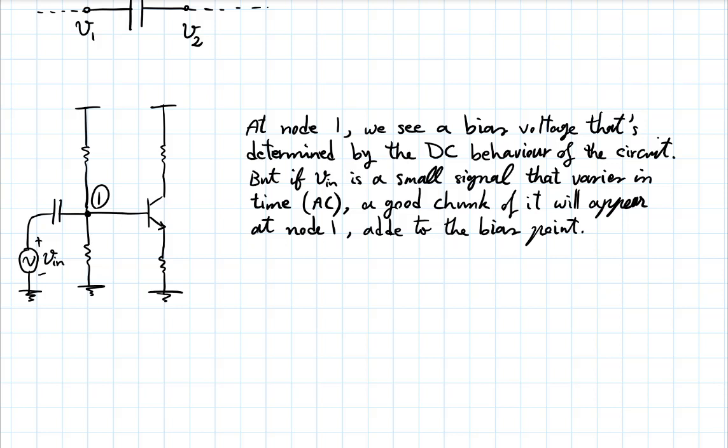Remember, if you want a capacitive circuit to respond fast, do you want a high time constant or a low time constant? Low time constant. So I want a small RC. So do I want a large capacitance or a small capacitance? Think about that.